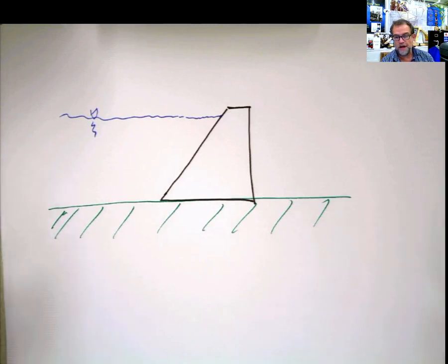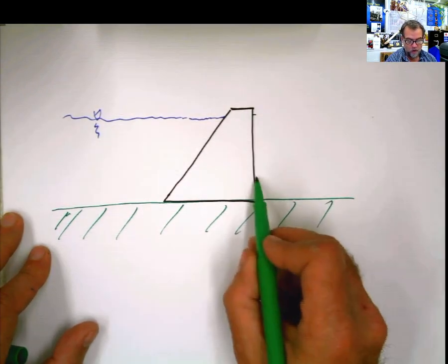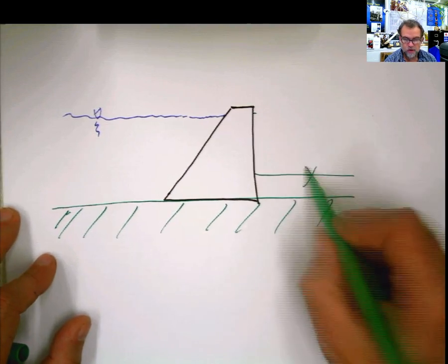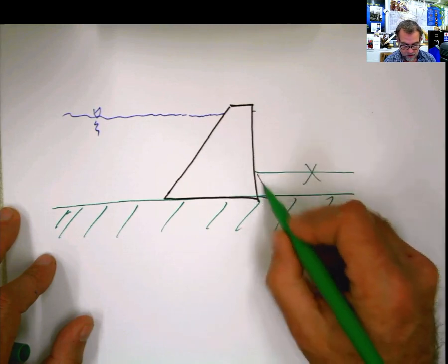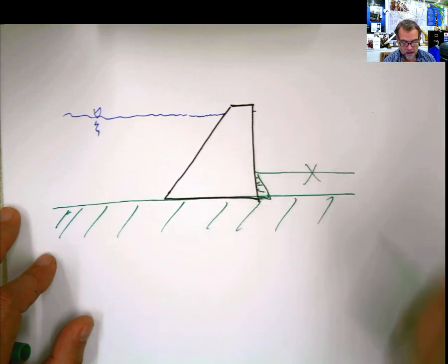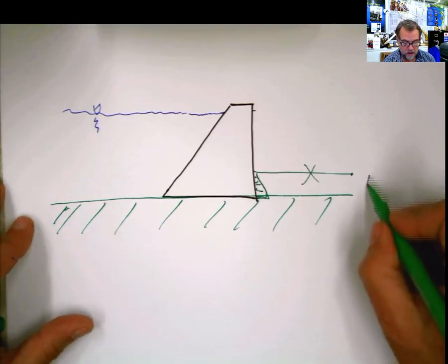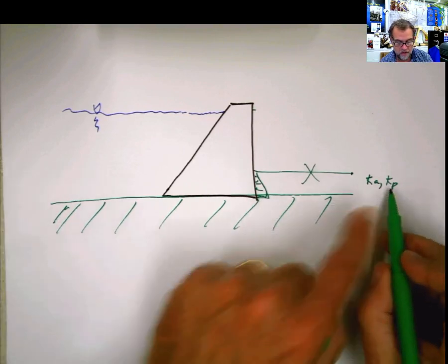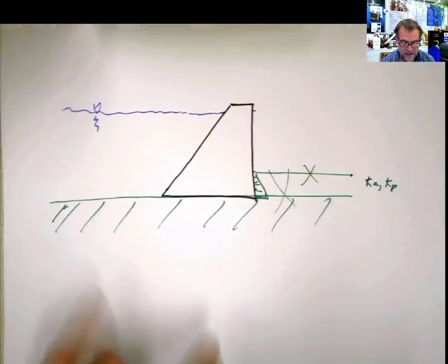And if you want to make it more real, you might have even also soil in this part, or part of soil in this part also, if you want to. But we are not considering soil. It's the same principle for soil. This is going to produce also a triangular load coming in this way, like if it was water, but the soil has to have friction, being granular soil, and then calculate coefficients which are called Ka or Kp, Rankine coefficients for that, and these coefficients are just multiplied by the same formulas for pressure. But this is not for statics, this is for geotech.